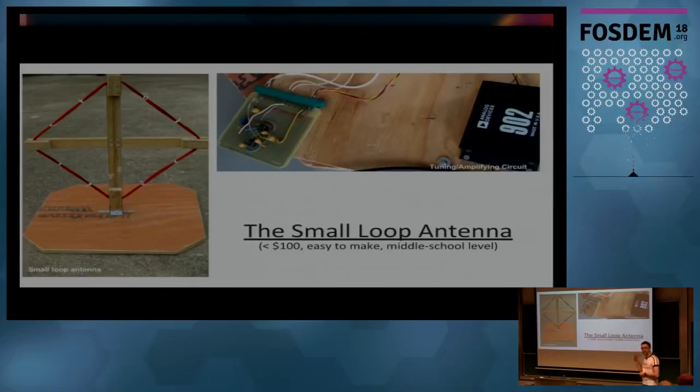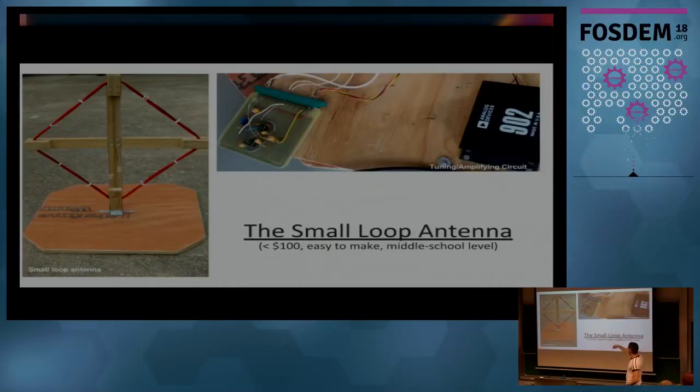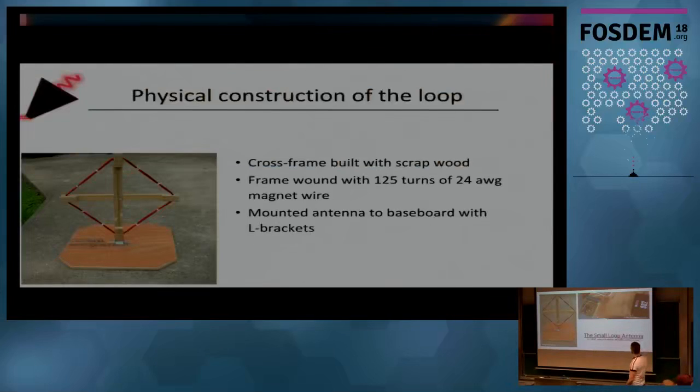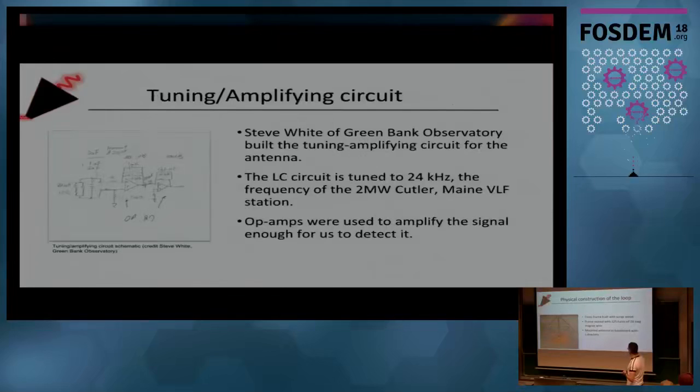It took a couple of iterations to figure out an easy way to do that. The actual antenna is basically a long wire. There is a tuning part, so ham it up effectively, and amplifiers. You start with just a frame, and the geometry matters, but the exact carpentry really does not. You wind a wire around it, and that's pretty much all you have to do.